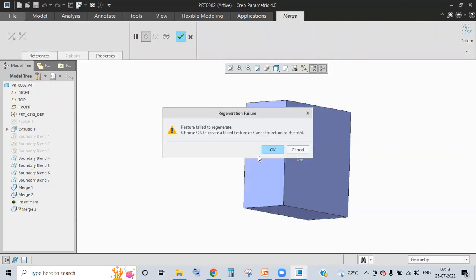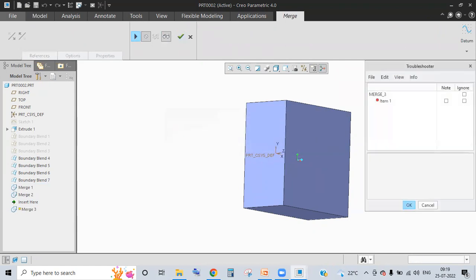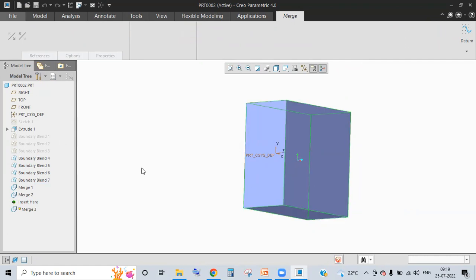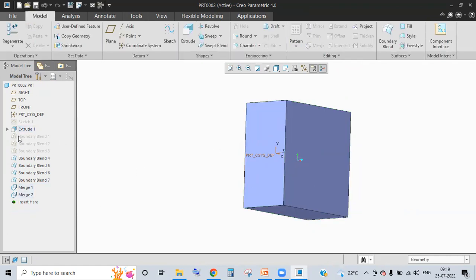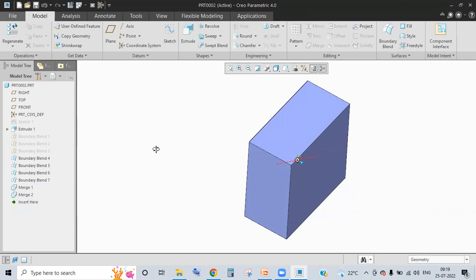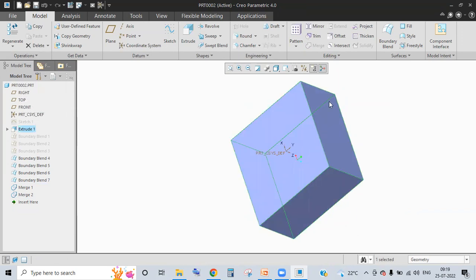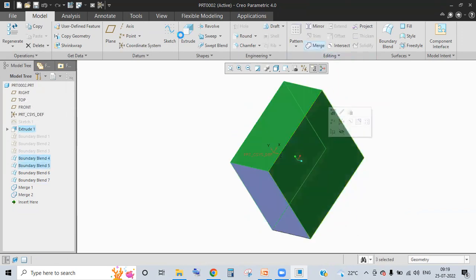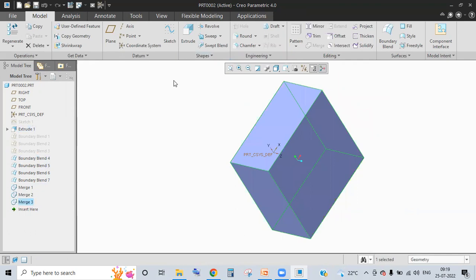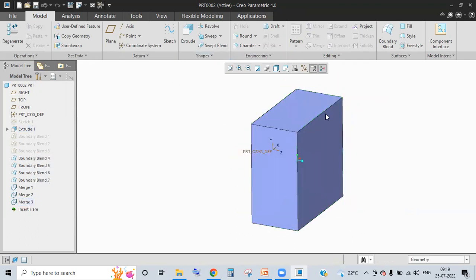Oops. Something fishy. Okay, once again, extrude. Select this, select this, select this, go to merge, it got merged. Okay, all merged. Then, since it is a closed single object, I can go to solidify.